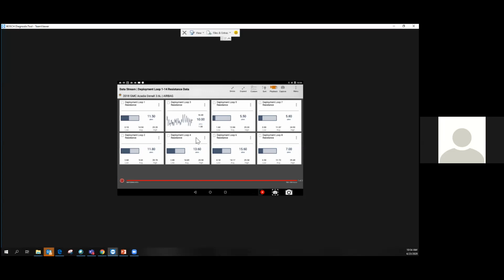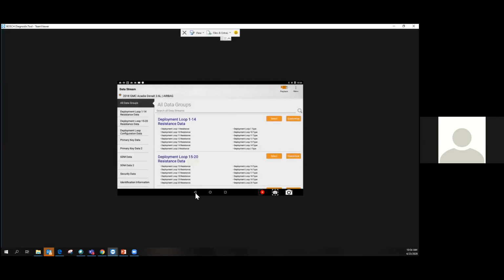And so this is something, obviously it takes years of experience to really know how to interpret this stuff. We will make it available to you, so you know how to look up this information, what kind of values you're looking for. Then you can turn on your live data, watch that voltage, watch those ohms, see what is out of spec from there. So you don't always have to get that multimeter out. We can watch that live data come straight to the tool from here.